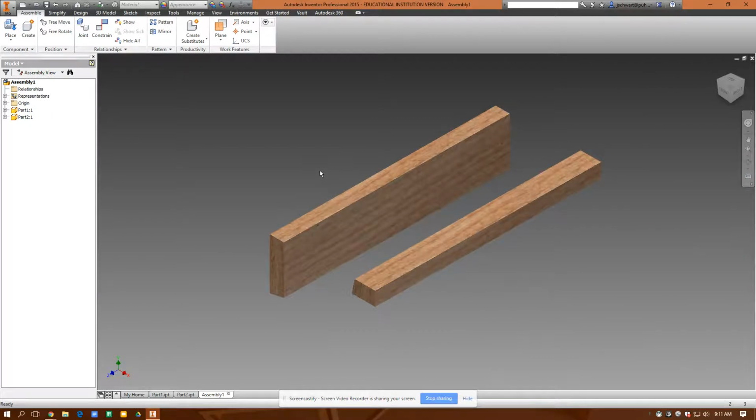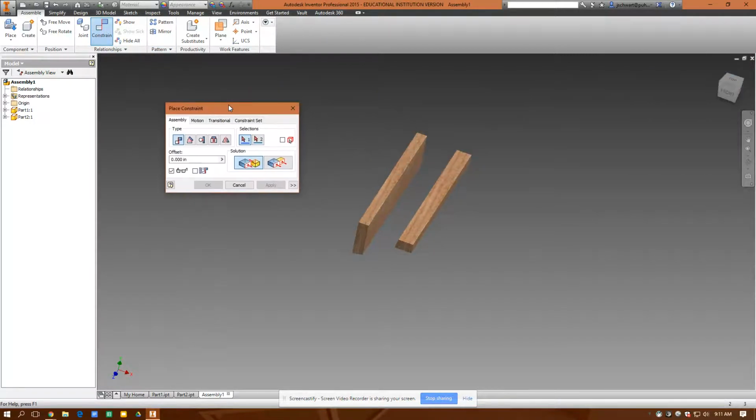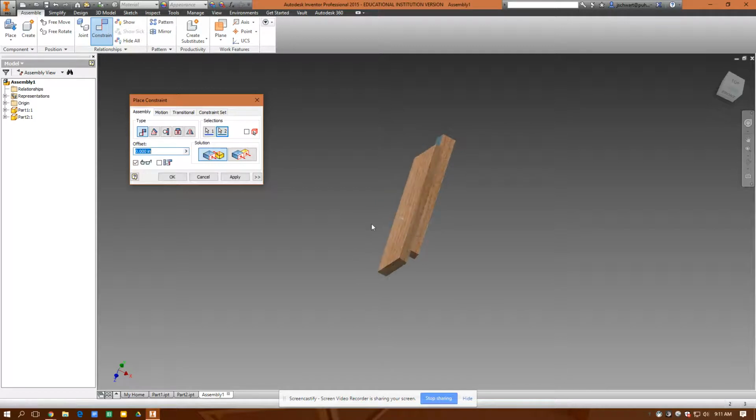And actually, I use a 3D mouse on this, so I could really grab my parts and move around. And I hold them together pretty similarly the way I did it when I built it. So that's called a constraint. And I'm going to constrain it. I get this pop-up menu here. I want to mate this back plane to that plane. That'll snap it on there.